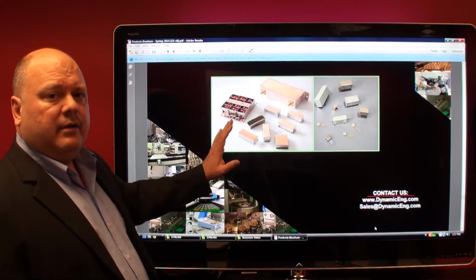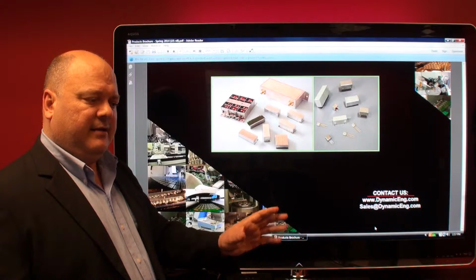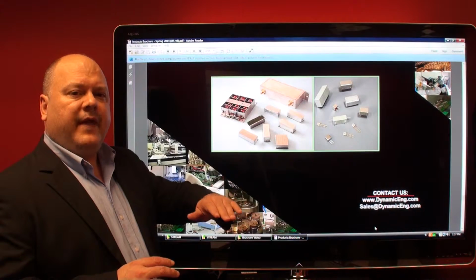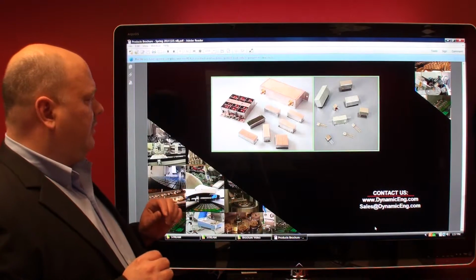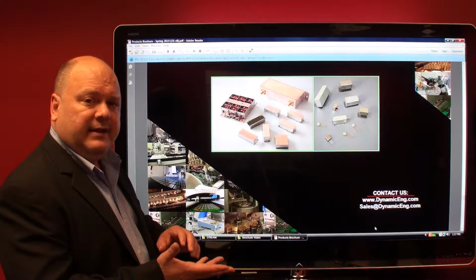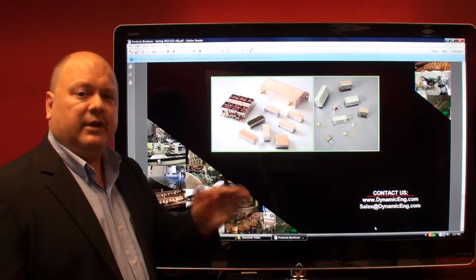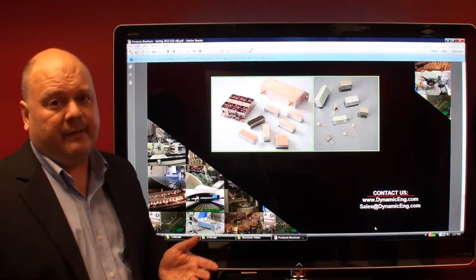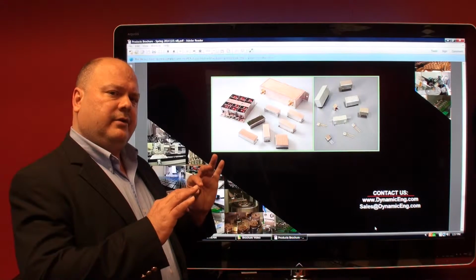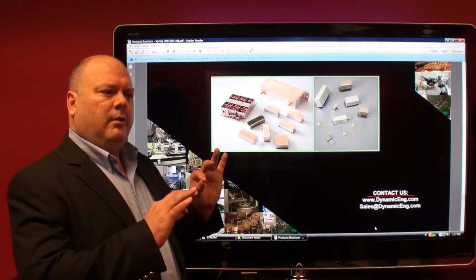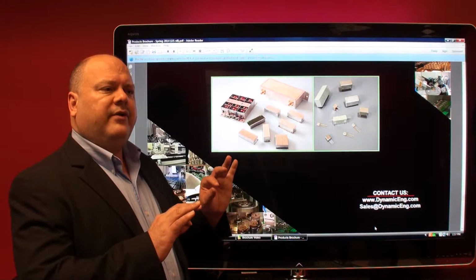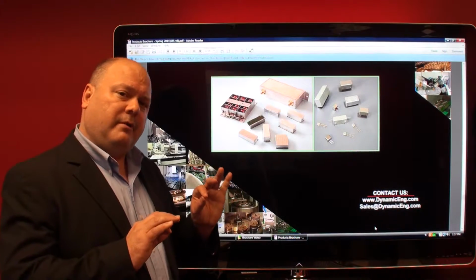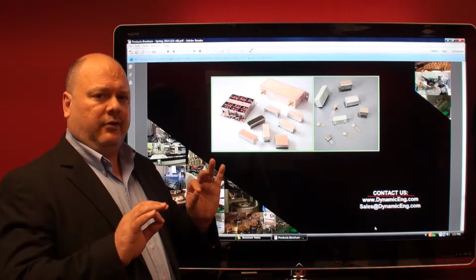Our factory then base plates, cleans the blanks, then adds the initial layer of metallization called the base plate. Then the final plating process occurs on the crystal blank itself to put the crystals in the crystal filter. All of them are at a certain offset frequency. If 4 crystals are used, for example, in the design, all 4 crystals will be related to each other with their offset frequencies, with their characteristic impedances. What I mean by that is their C1, their motional capacitance, will be related to each other.